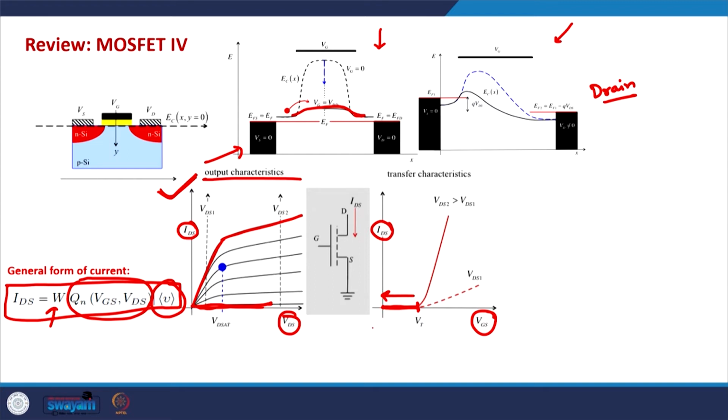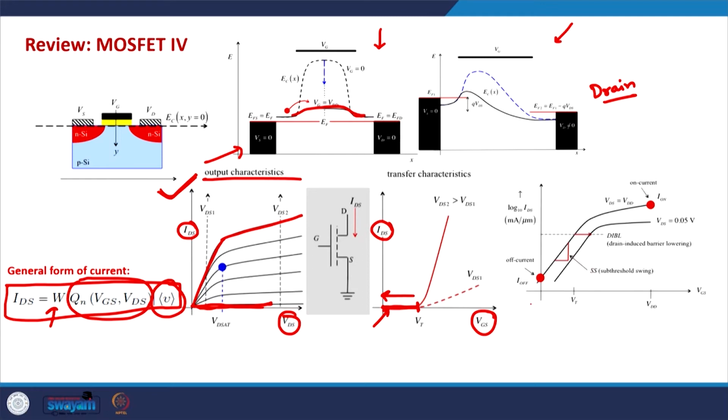And if, instead of plotting IDS versus VGS, we plot log IDS, the logarithmic function of IDS, this will give us a better, zoomed in picture of the current in this regime, and this is how the current will look when we have log10 IDS on the y axis and VGS on the x axis.